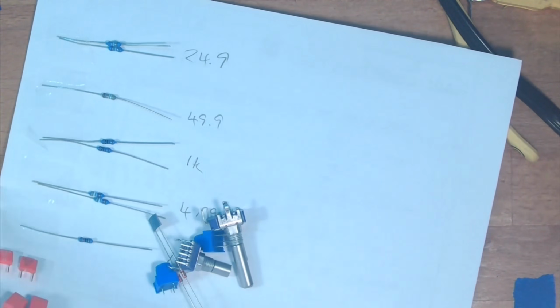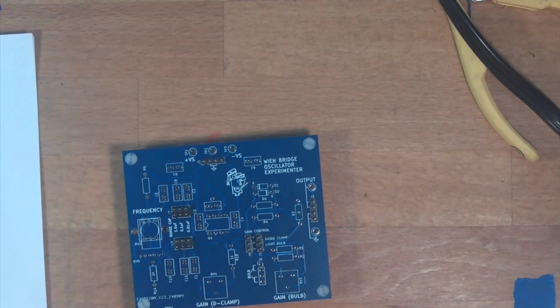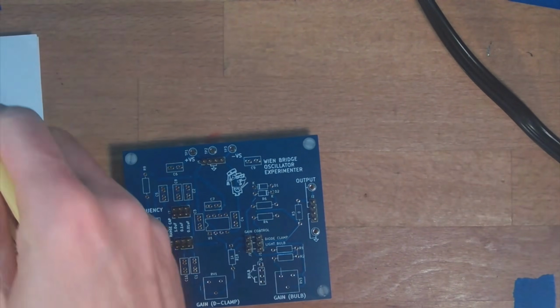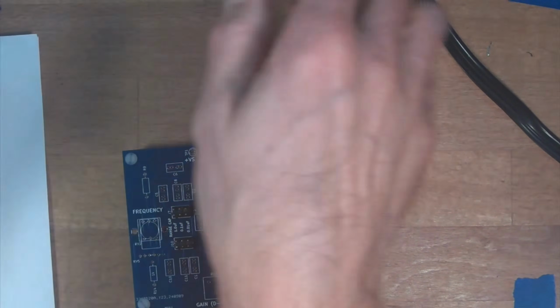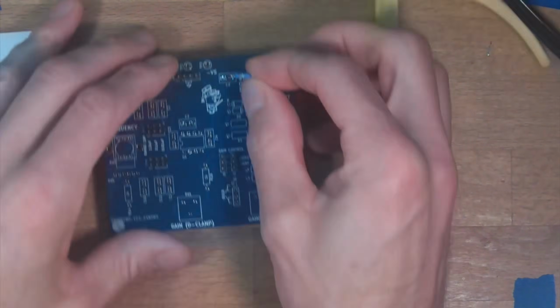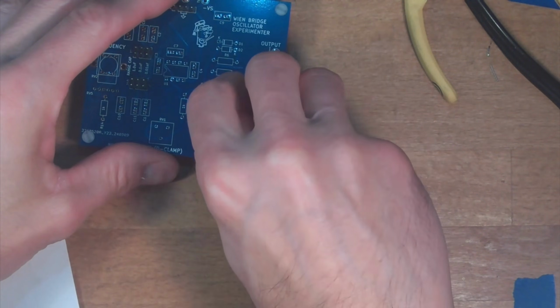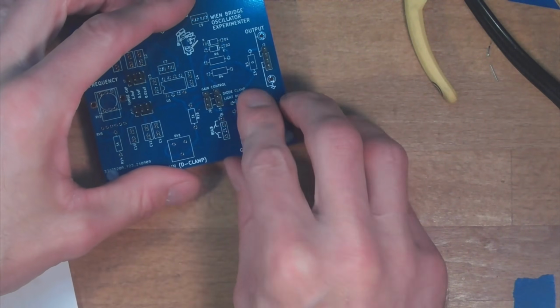All right, so I've got my components laid out here, ready to rock and roll. So I'm going to keep these over to the side and I'll talk you through it. All right, so we've got some 25 ohm resistors. I'm going to bend these leads, and just so that they don't touch the desk, I'm going to clip these as I go along. And let's see, it looks like that is R1 and R2. You don't really have to be this picky about it, but I try to keep these guys in the same direction so you can read the color code here.